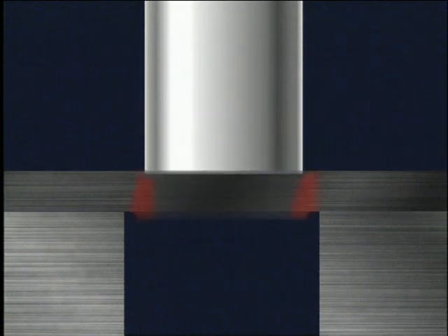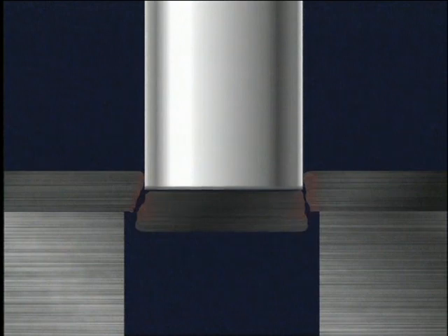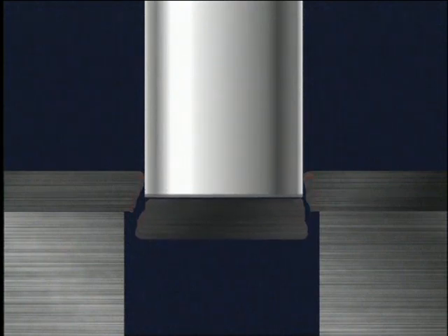During punching, the stock is stressed between the cutting edges of the punch and the die. As the punch penetrates the material, stresses build up until fracture occurs. Close inspection of a die-cut edge of sheet metal stock reveals a burnished edge where the punch penetrated the stock, followed by a rough edge where fracture occurred.